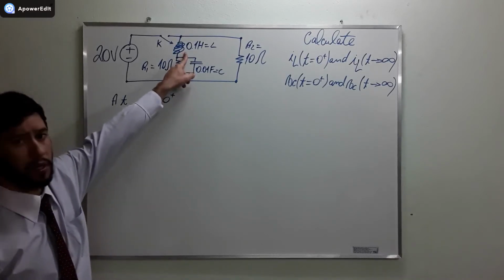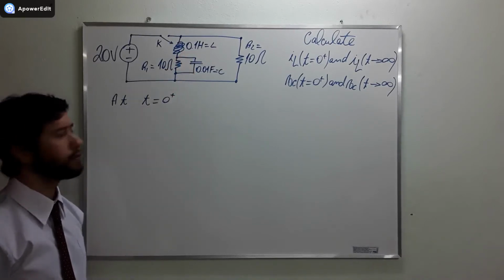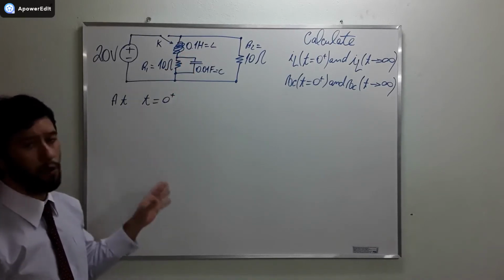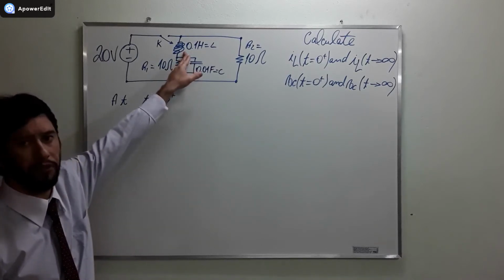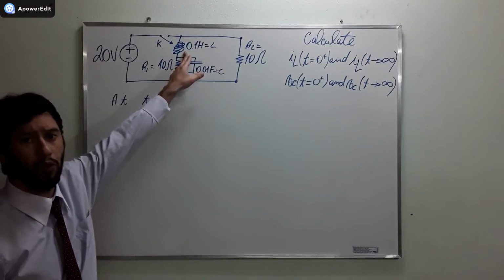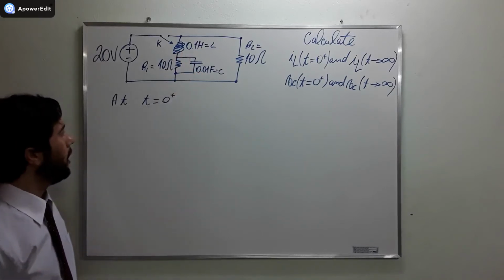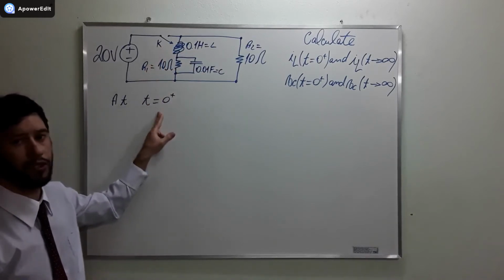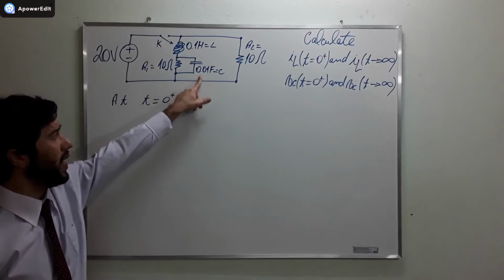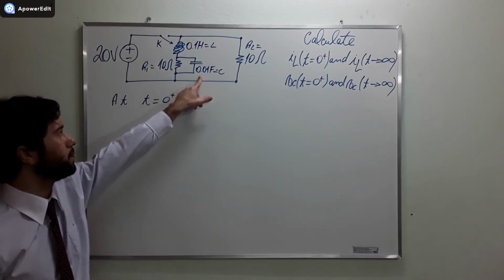The inductor behaves as an open circuit. The current will not pass through the inductor. And at t equal to 0 plus, the capacitor behaves as a short circuit.